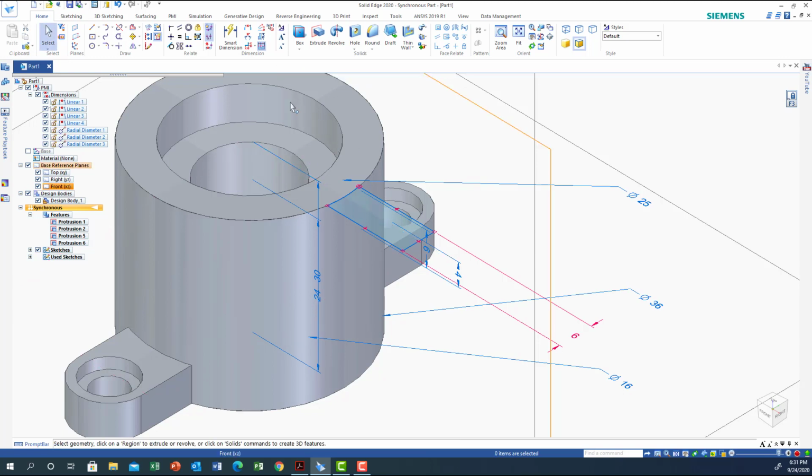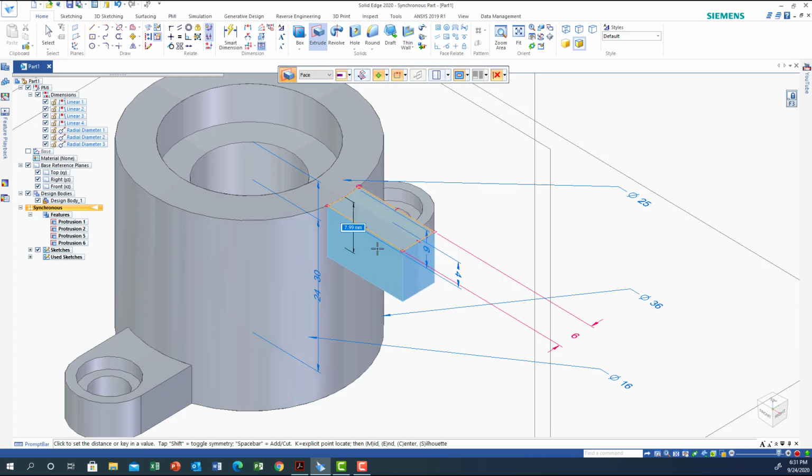Now I need to do the extrusion, so I'm gonna go to extrusion. It's plus face, this face, right click, and I'm gonna go down. Okay, so I'm gonna go down, so right click here. Okay, right click and go down. How much is gonna be? 12.